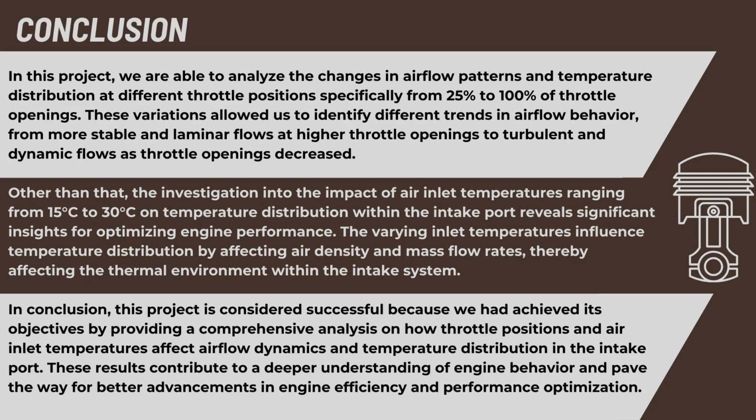For the conclusion, in this project, we are able to analyze the changes in airflow patterns and temperature distribution at different throttle positions, specifically from 25% to 100% of throttle openings. This variation allows us to identify different trends in airflow behaviors, from more stable and laminar flow at higher throttle openings to turbulent and laminar flows as throttle openings decrease.